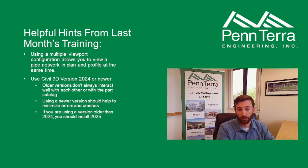The other thing that's really important when we're talking about pipe networks is to use at least version 2024 or newer. We've had issues, especially with the storm sewer pipe networks with older versions, even to the point where if one person on a project team is using 2024 or 25 and somebody else opens it and tries to interact and they're using 2022, it can really mess things up for everybody. So I would caution that. If you are using something older than 2024, I would recommend at this point to just install 2025. It's working pretty well and it's running faster than 2024 is for me, so you can keep that in mind.